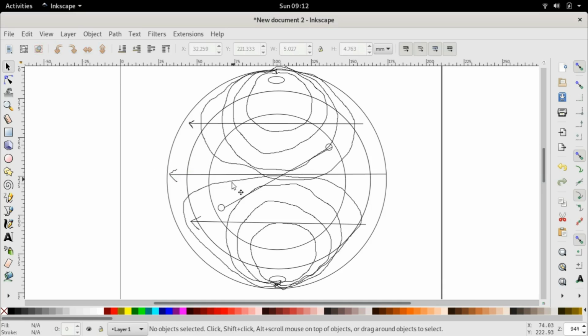Right, this is the net flux. This is the net stator flux which is produced by the entire stator coil winding, and this is perfectly understandable. For example, if this is a coil which is wound, you will find that the entire coil is going to produce a net effective flux which is moving from the right to the left. Because remember, again, it requires a little imagination, but if I were to flip this diagram and